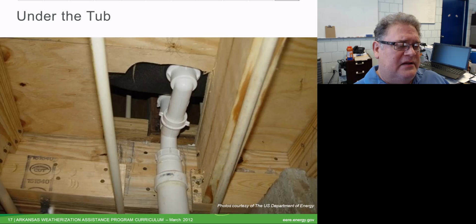What winds up happening, though, is we create building science issues or broken buildings. We've got a big hole for varmints to pass through, so this hole doesn't meet code. It should have been rodent-proofed. But the other issue that we have here is that we've got a giant hole for air to pass through. We need to cover that, so we'd cut metal or wood or something to cover that.